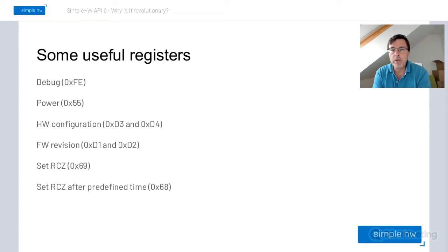Then we have the power. You can control it in cases where you have really good Sigfox coverage and you want to save battery life. So you can limit the voltage and attenuation. You can play with attenuation of the transceiver, and you can limit the output of the transceiver, and you can achieve even higher battery life, especially if you need more than 30,000 messages.